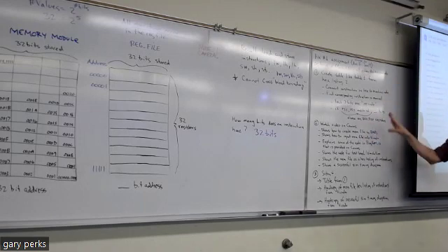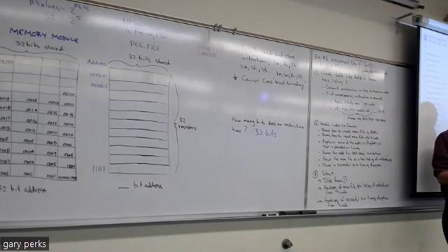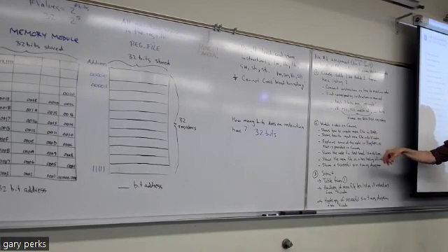Okay, the next thing, once you do that, what I recommend is watch the video I have on Canvas, because it steps you through what you have to do after that. It shows you how to create a mem file. You're going to see it's very simple, actually. It's only like 3 clicks. So you generate a mem file, and then it shows you how to input that mem file into Vivado, and it's just like adding a design source.